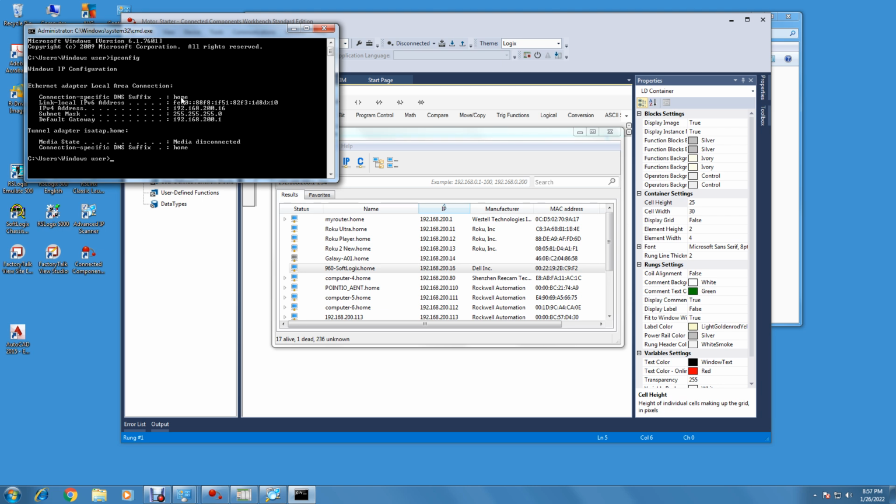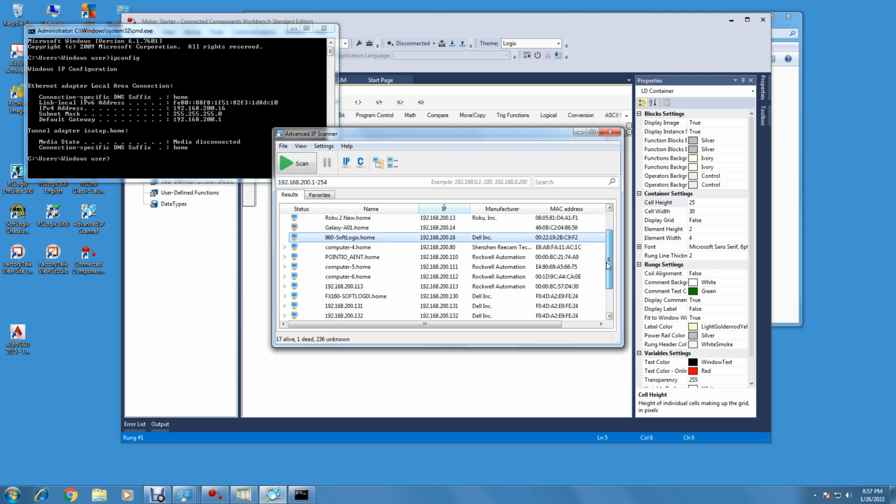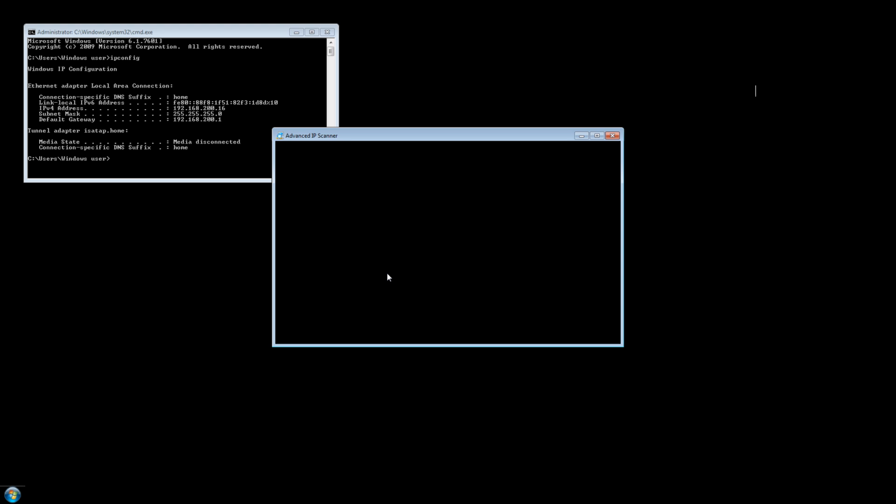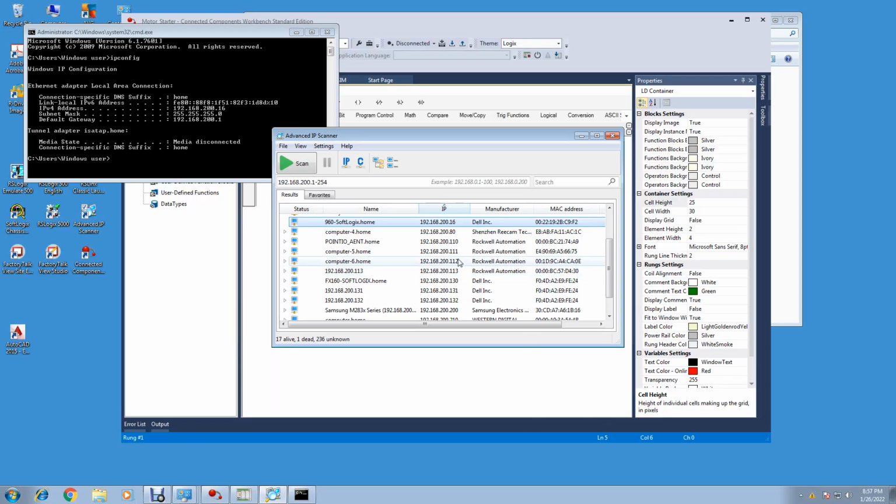We can add some addresses to this computer here. This computer needs a bunch of addresses, and as you see, I've got 16, then I've got 80, and here I've got my point IO, and this is my flex IO, it's at 110, and this is my frequency drive, it's at 112, and then there's another couple pieces of Rockwell hardware here up to 113.